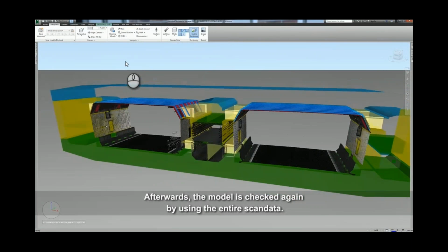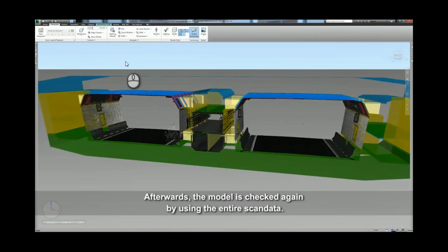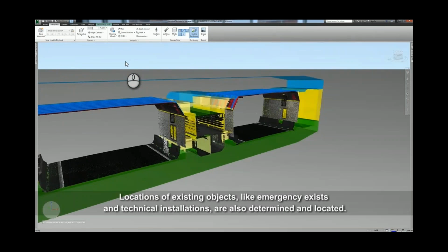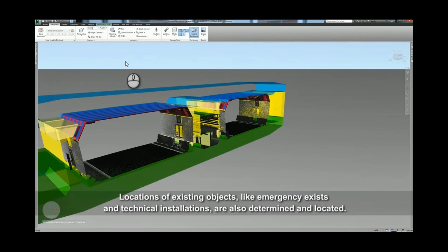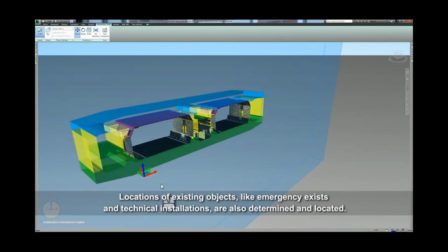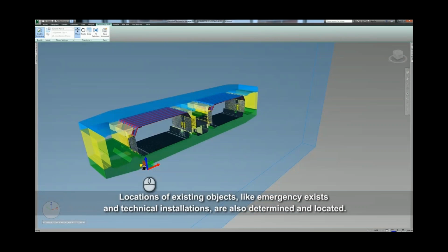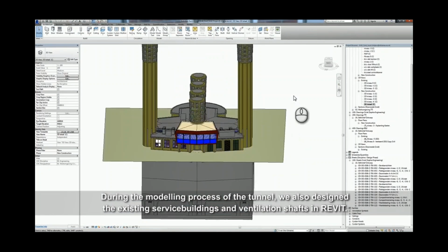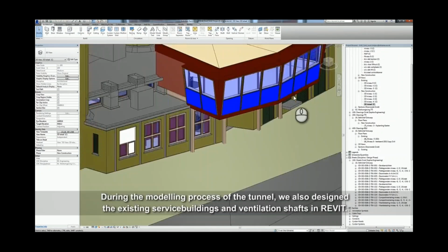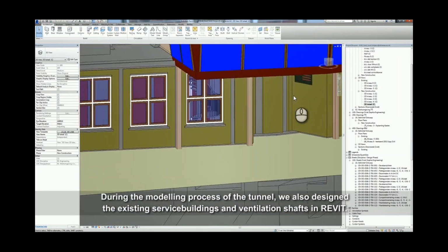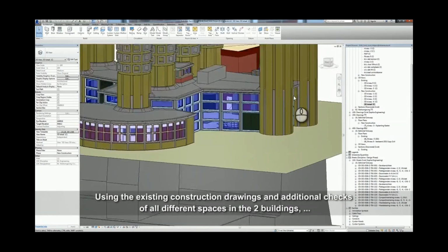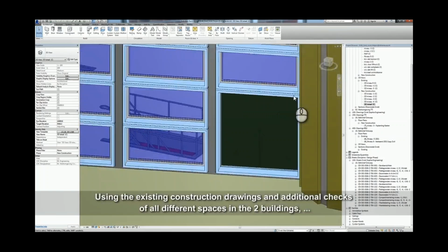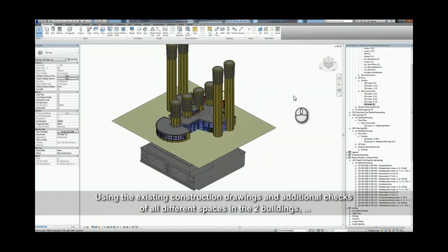Here you can see this is the complex tunnel structure. So here we can see that now in Navisworks, as well as the point cloud there. And they're also using the really nice sectioning tool, so we can drag the section up and down, especially slicing through that model. There's also a detailed Revit building within this Navisworks model that's going to sit there. So again, just showing how it's aggregating lots of different data together, and that can all be seen in the one environment.